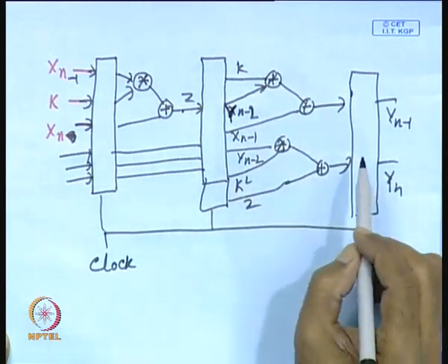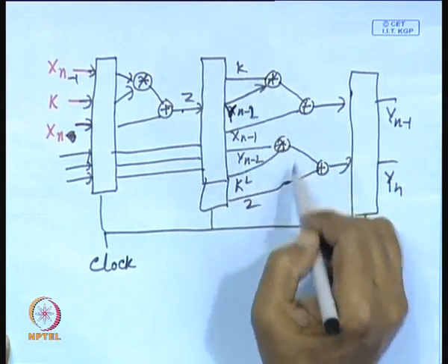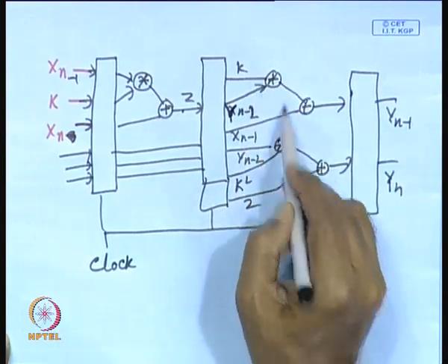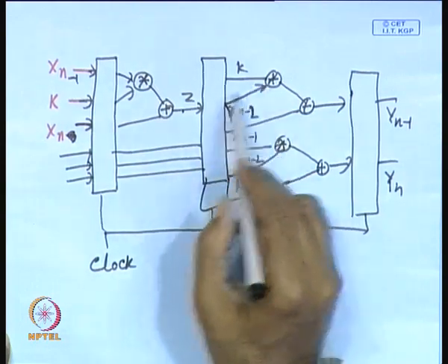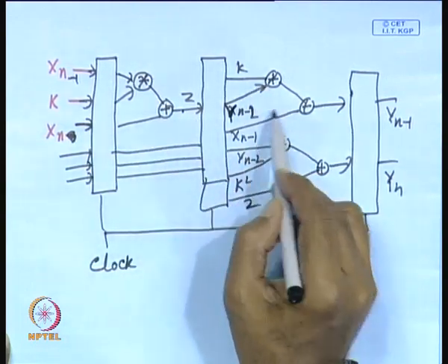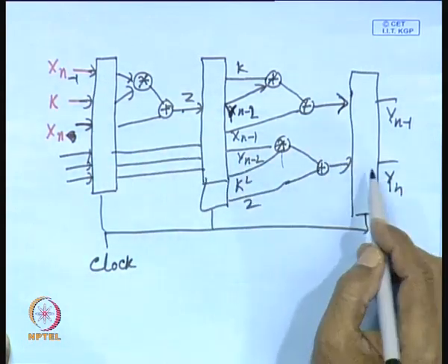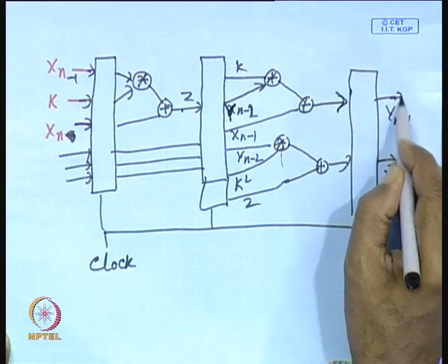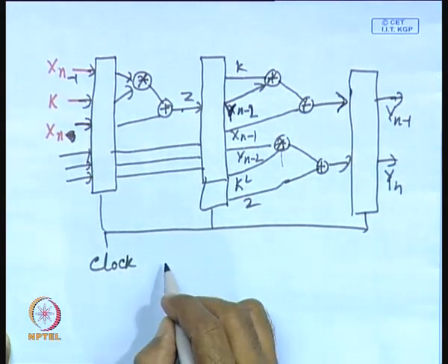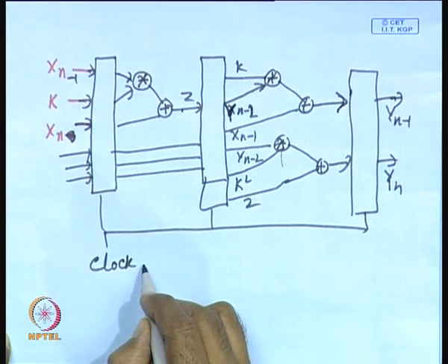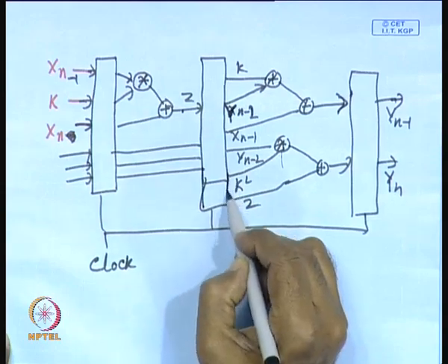So, you can see here each of these stages will require 2 clock cycles, because you have got 2 stages. So, this stage will require 2 clock cycles, that means the delay for each stage is equivalent to 2 clock cycles. That means, after the pipeline is filled up, it will produce output at an interval of 2 clock cycles of the original circuit. That means the clock frequency is twice that of the original circuit.